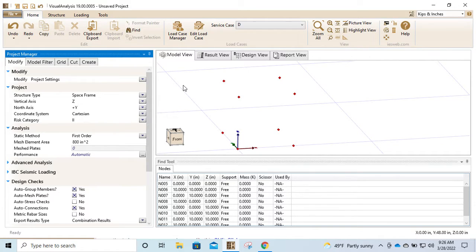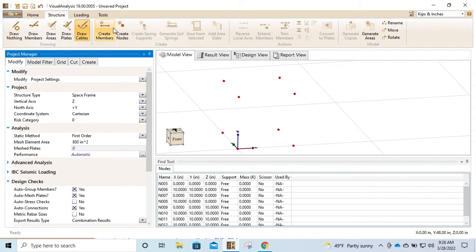All right, what else we got? So we're back to the structure ribbon. We can generate all these things. Some of the extra stuff that's not highlighted here, and mainly it's because I don't have things there to generate it, but we can add spring supports, okay? We can give our model, say, a torsional spring or a linear spring. What would that mean? Well,